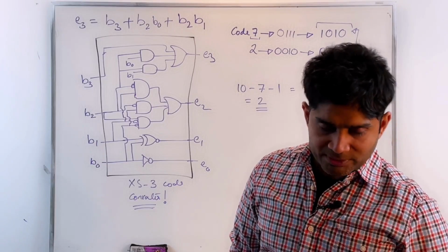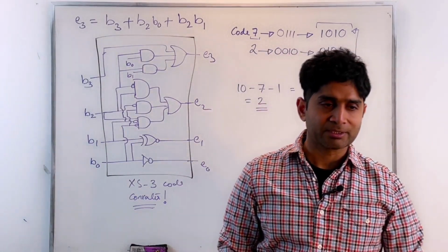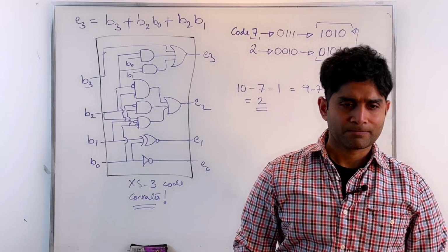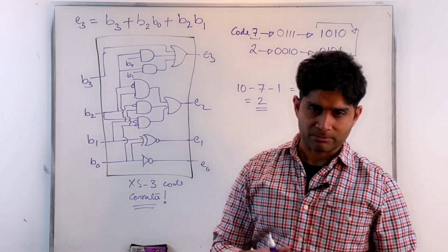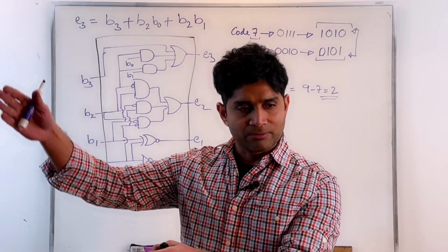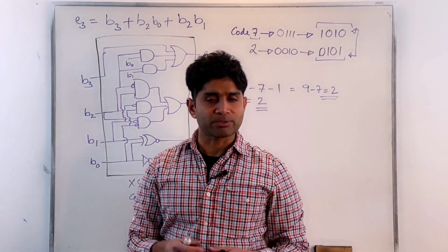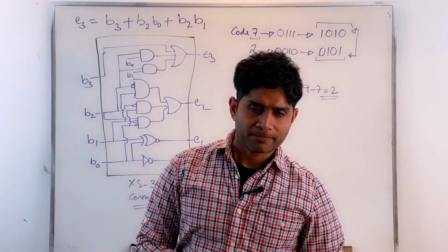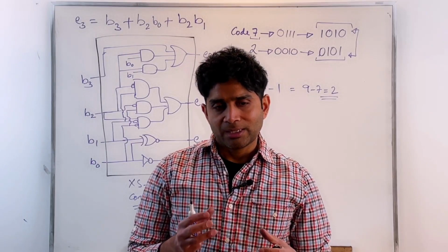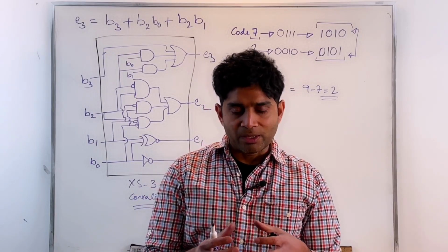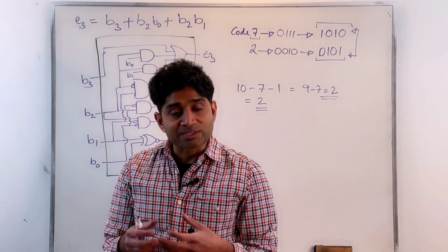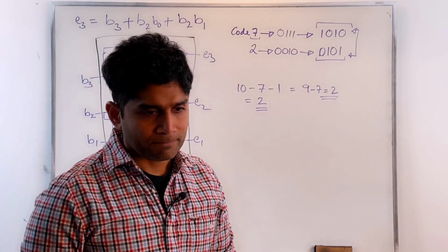So that was our first example of a design of a combinational circuit given a problem specification. And you've seen the approach I've taken, going from the first step, level 0 diagram, to the truth table, and from the truth table to the K-map approach, and obtaining the simplified function. So now we are basically putting together those Lego blocks. We're learning the technique to put them together in the right format to serve the purpose. All right.